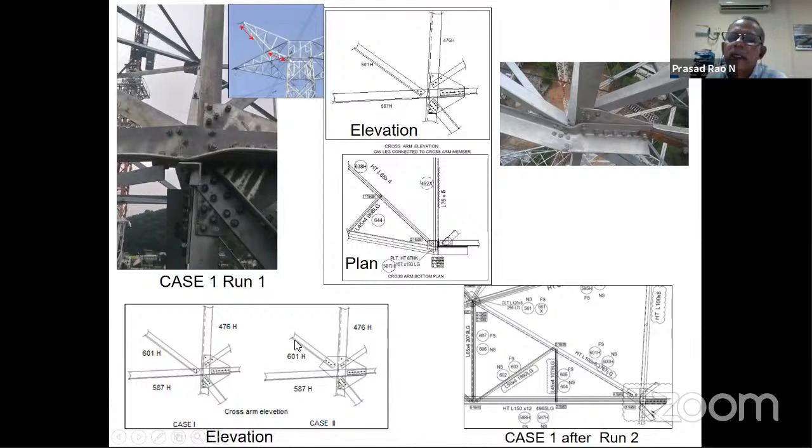Unless you do a post-mortem, you will not know this while designing, because we finally come up with only a line sketch. This line sketch is given to the detailer, and the number of bolts and the force will be specified. If the detailer has good knowledge of detailing, then it will be detailed properly.